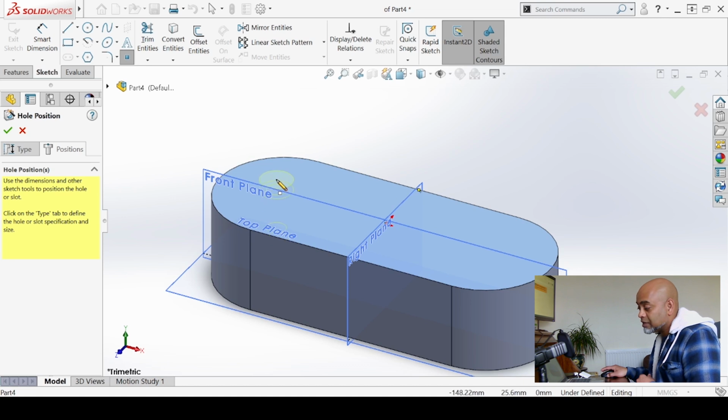And SolidWorks has brought us into auto. I didn't do anything magical here. All I did is select the flat surface there, and SolidWorks will bring us into the sketch menu, where we are now adding a point. What this allows us to do is wherever I drop the point now, it's going to drill that hole of that shape. Now I can't see properly from here, but I'm going to use my best judgment and probably drop